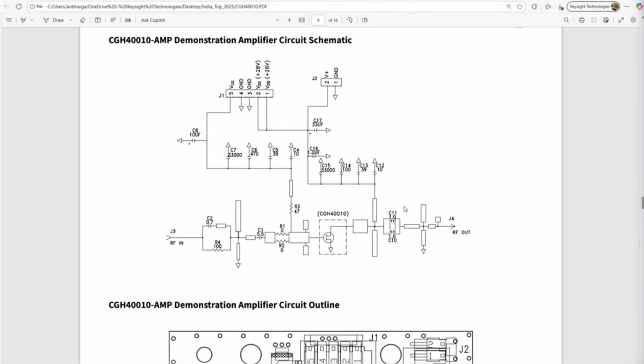So one good starting point to remember, whichever way you are going to assemble your power amplifier, you should simulate or you should plan like that from the very beginning. All right. So if you know you are going to mount two things in parallel, make sure in your circuit simulation, in your layout design, all these aspects are taken care of. Think of the destination, how the final product will be, and that is your starting point.